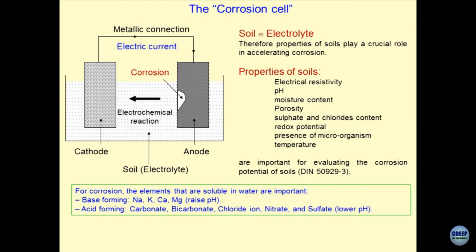Concentration of bacteria at one place in the soil mass would connote something different than at another place. And if you remember, I was talking long back that nowadays people are studying microbial flushing also. So, from one place the concentration of microbes gets flushed out and might get accumulated at some other place. So, by virtue of anything, if a situation of this sort occurs that there is a cathode formation and anode formation in the soil mass which is wet, and because of being wet the electrolyte is present in the soils, there is corrosion of a certain portion of the buried element. So, now I would say that this anode is a pipeline, let us say, or a foundation or a pile, clear. So, the moment this type of situation gets triggered because of environmental parameters, the chances are that certain portion of the anode might get eaten up, and that is what the corrosion is.